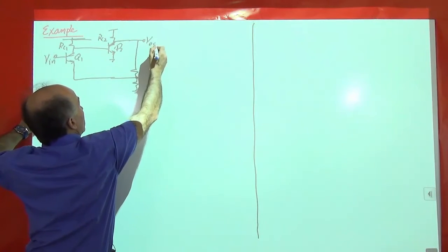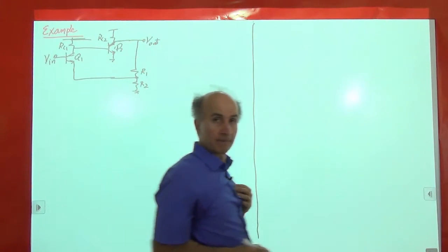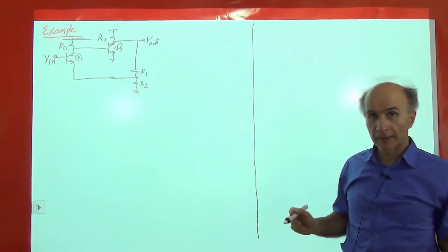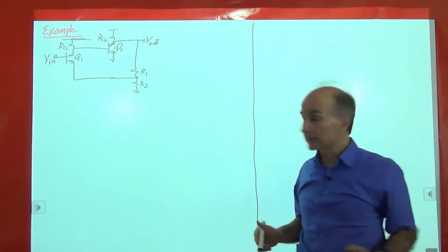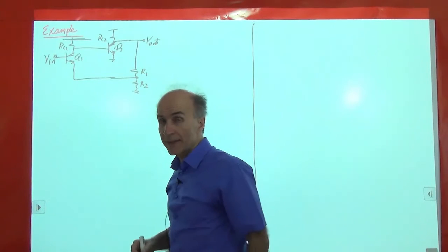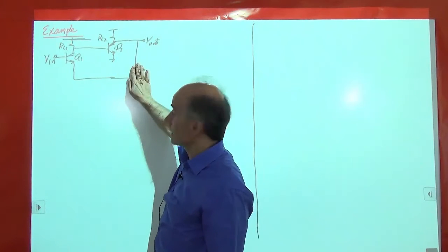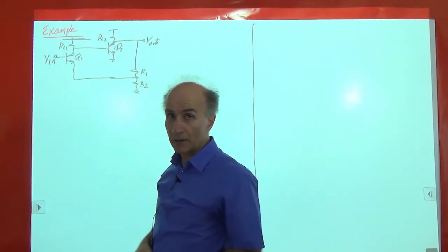Okay, so this is also a voltage feedback circuit. We want to break the loop properly, right? I'm interested in the open loop gain and input impedance and output impedance and all of that. So how do we do that? Remember the previous table said that if we have voltage feedback, we make a copy of this over here, a copy of it over here, and then we just have to connect our ports properly.